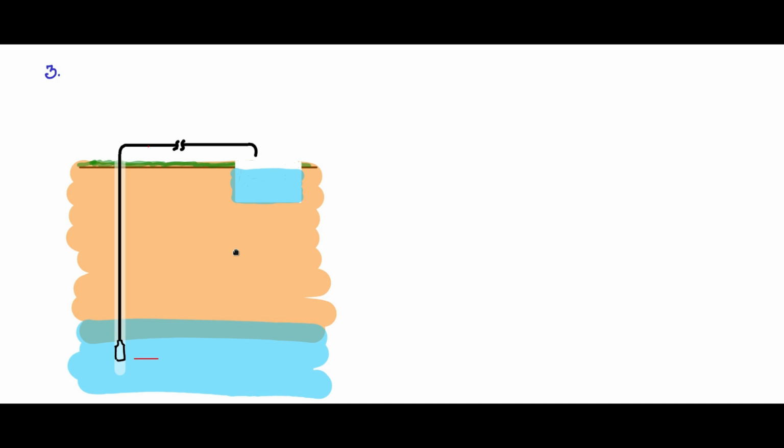and let us take some typical depths. So around 600 feet. So 600 feet depth borewell is pretty common. So this entire depth is called the delivery head. There is no suction head. Then the water has to travel this horizontal distance in the pipe depending upon where the sump is located. And let me take a typical example of around 200 feet distance horizontal travel.